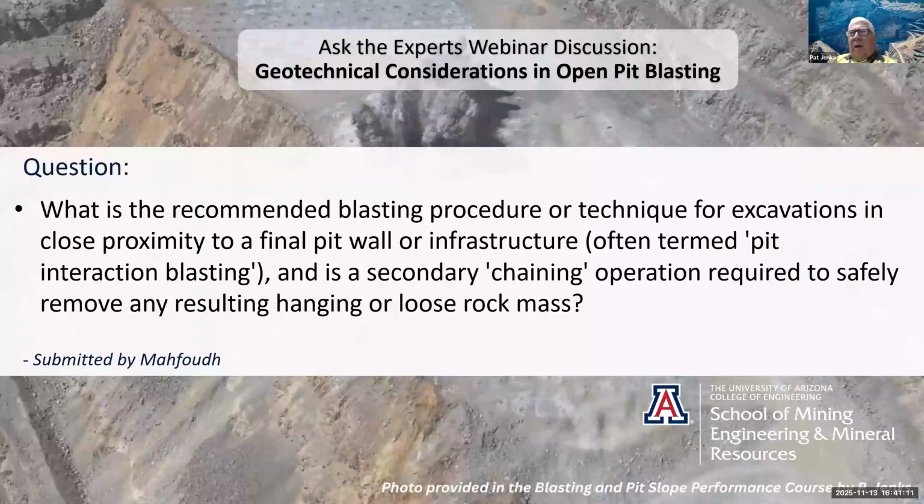So I think it's going to be a case by case basis, but in any situation, you're going to have to scale, and scale properly, whether that's with a chain being pulled by a dozer or hung from an excavator, or using a long reach excavator to scale to minimize rolling rock risk.